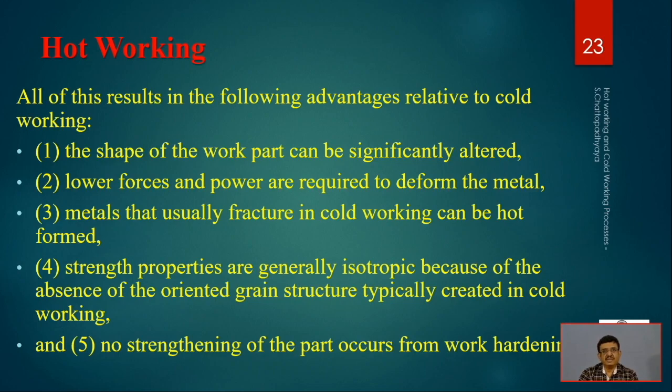All of this results in the following advantages: the shape of the work part can be easily altered, so it is easily deformable. Lower forces and power are required, that is, the machines will be much more miniaturized than the conventional ones, because less force will be required. Metals that usually fracture in cold working, because of the huge amount of stress at room temperature, cannot be fractured at lower force.